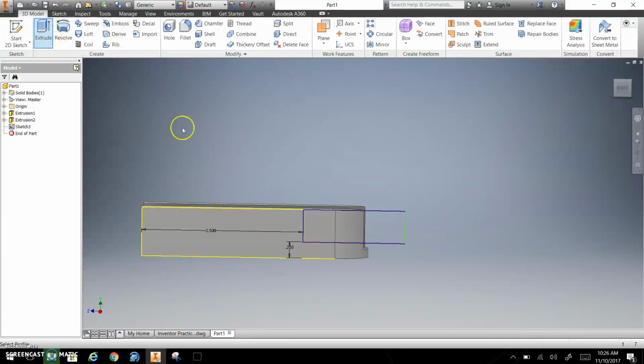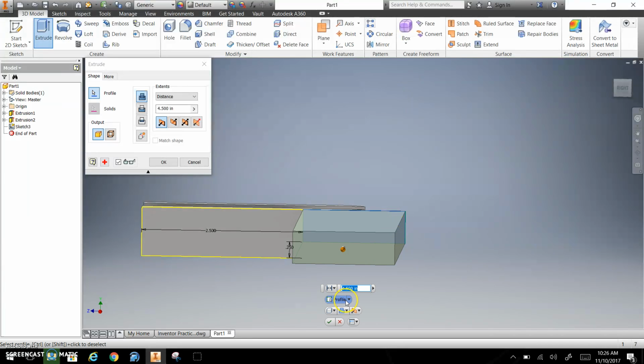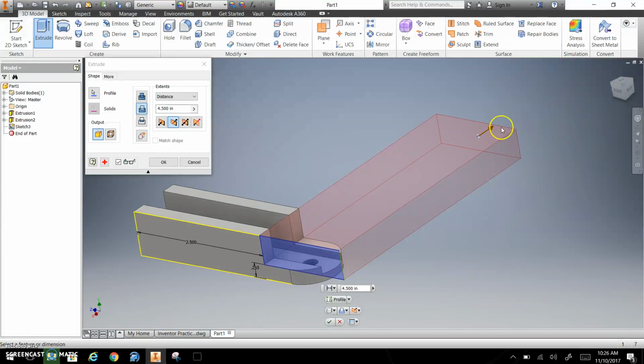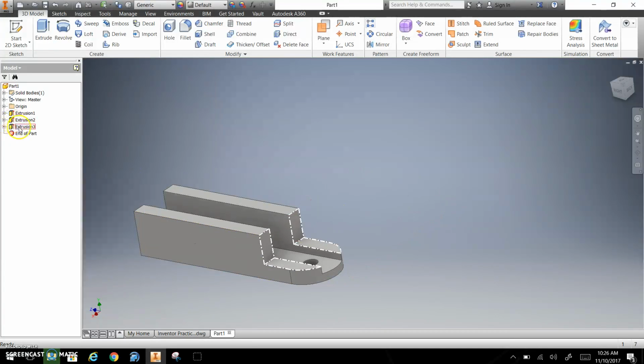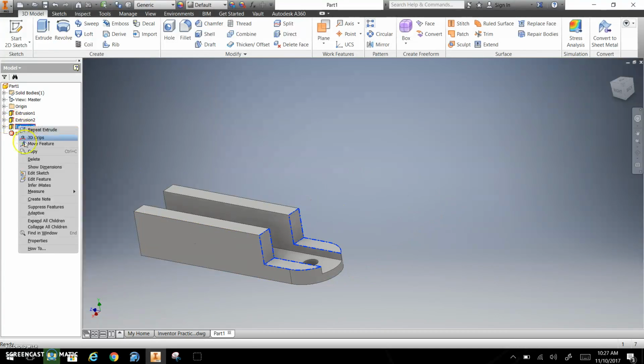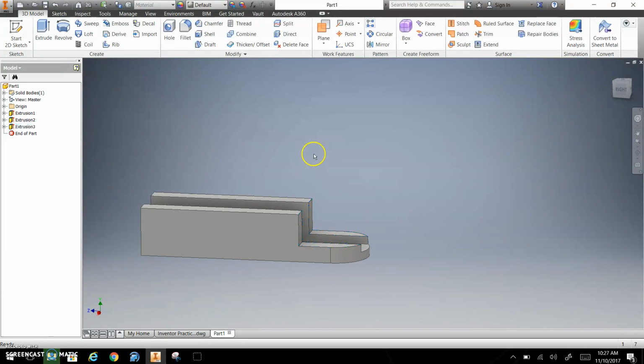And then you're going to cut this, extrude, click on what you want to extrude, change it to cut, and then pull it through. It already did that. Maybe yours will do this, so you got to pull it through there. And once again, you can always go back and edit these. You can delete them if you mess up. You can do a Control Z.